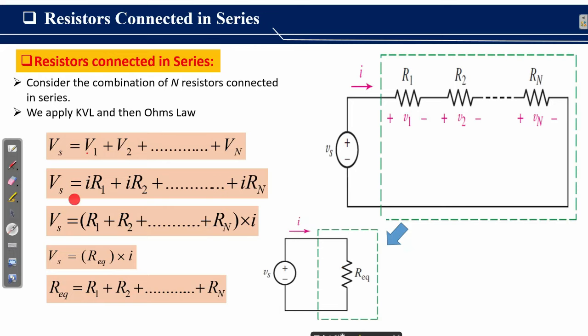For this, we need to understand this mathematical work. We know that these resistances are connected in series to the applied voltage source Vs, making one closed loop or path. So it's a perfect example to apply Kirchhoff voltage law on it. And for Kirchhoff voltage law, I recommend to refer to lecture 5 of this course. After applying Kirchhoff voltage law in a clockwise direction, we get this expression. Vs is equal to V1 plus V2 plus Vn.